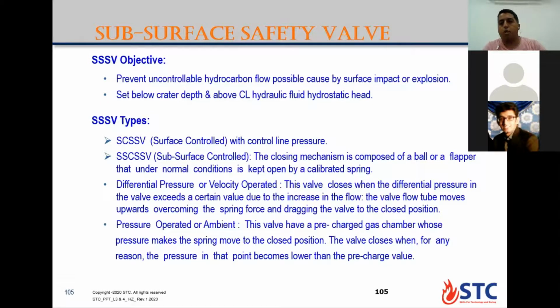So I need to run the slickline to retrieve this type of subsurface safety valve, charge or check the value for pressure differential, and run back again. So this subsurface control is usually not a common type now during operation because it's controlled from the downhole. But the best one, and the most commonly used now, is the surface control from the control line at the surface, which is easy to operate.